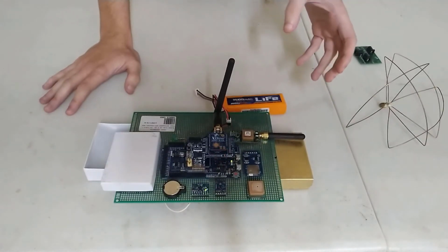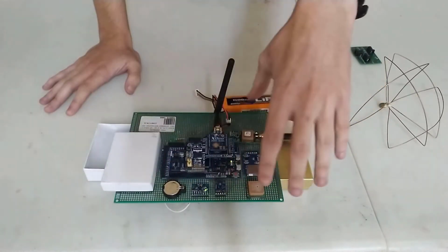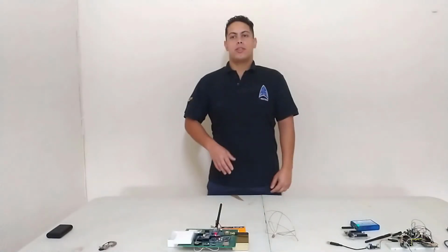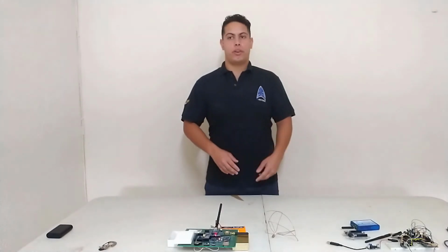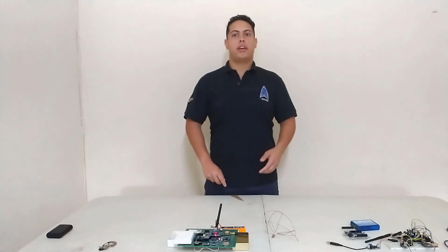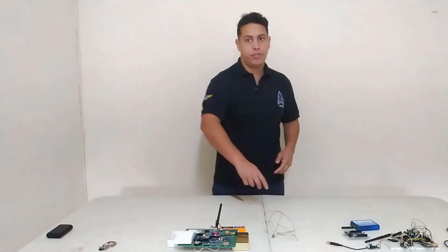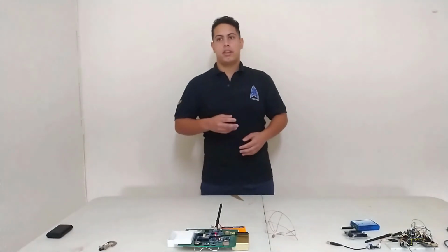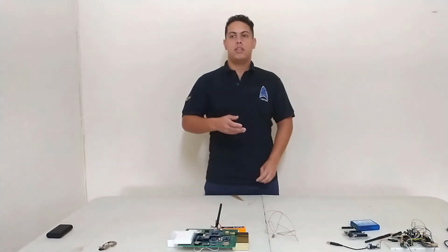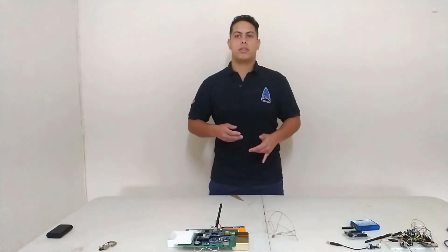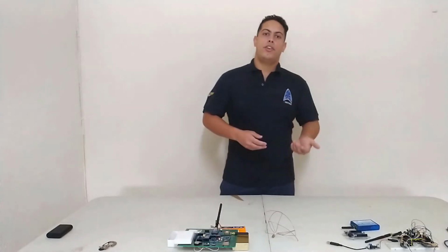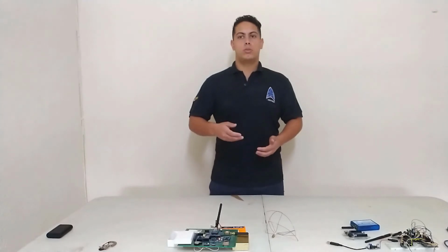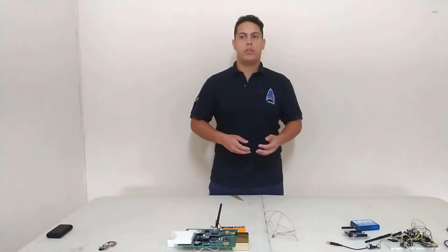As a matter of redundancy, we utilize two assemblies like this one, so we utilize two main boards with all of their components. By using a high power XBee of 200 milliwatts with a rubber duck 3 dBi antenna and receiving with a 5 dBi cloverleaf antenna and an XBee receiver sensitivity of minus 110 dBm at 10 kilobits, it's possible to retrieve the signal from the transmitter at distances as far as 50 kilometers if necessary. Therefore, even considering the nose cone and environment noise, we expect to have a stable and smooth data transmission.